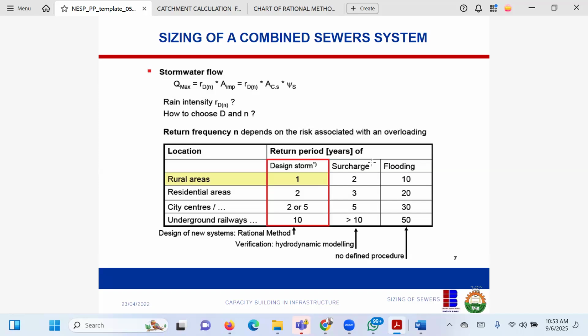Meanwhile, let me also say this. It is not the duration of the rain that causes flooding. It is the initial intensity within the first 10, 15 minutes. Most times you can see rain will rain in Lagos from morning to night. You won't see flooding. The one that will cause flooding, after 15 minutes, it's already giving you 140 on your gauge. Flash flood. So once you declare 140 within 10 minutes, your early warning system, which we don't have anyway, you ring the alarm.